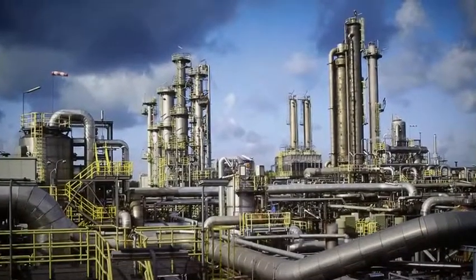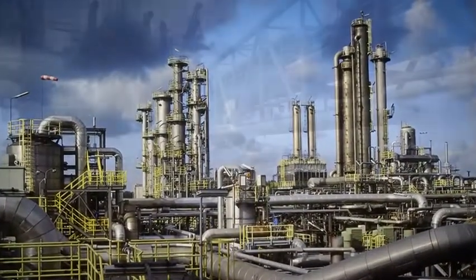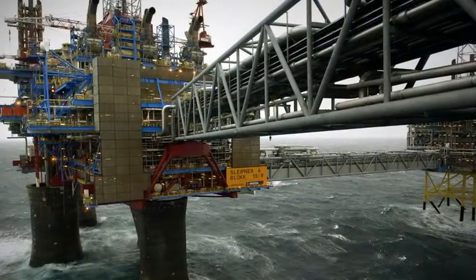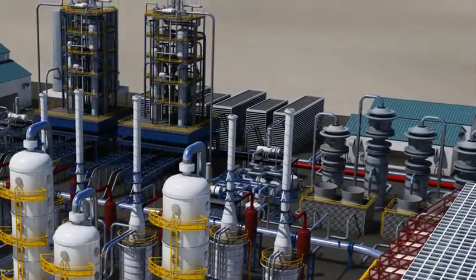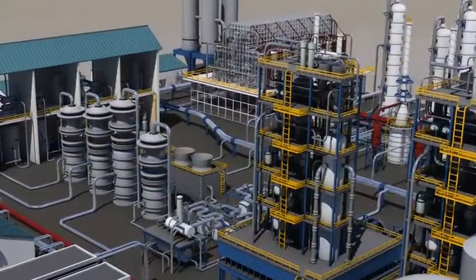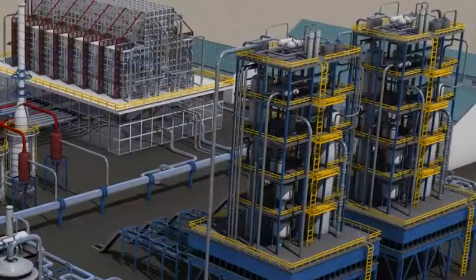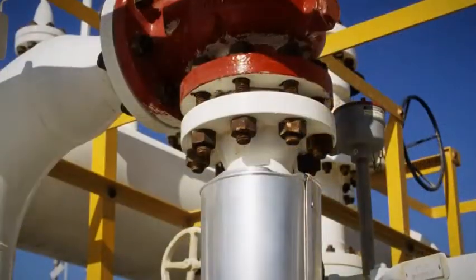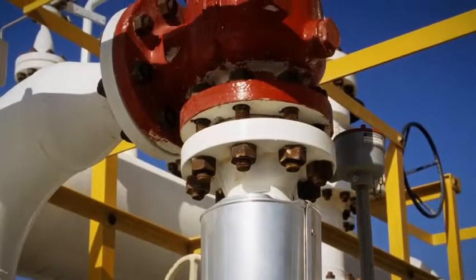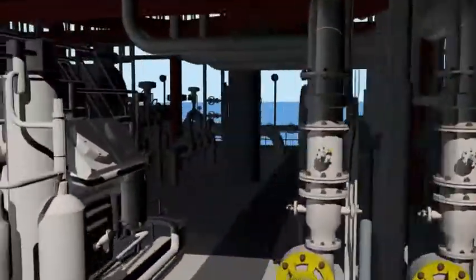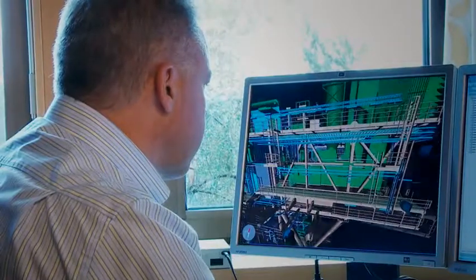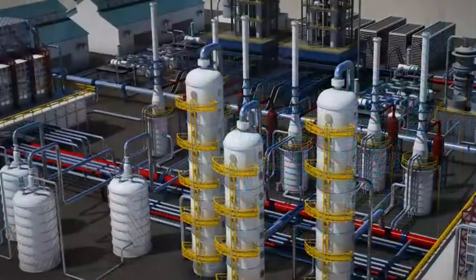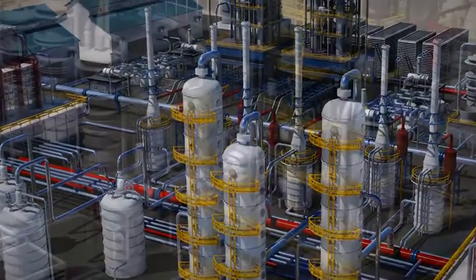Brownfield projects, those performed on existing plants, are the vast majority of projects now planned or executed worldwide. A brownfield project's workflow differs from a greenfield or new project's workflow in that the project must accurately model tie-in points to existing pipes and equipment for new equipment and piping relative to existing components and removal of components no longer needed. To accurately depict these tie-in points, a 3D model of the existing plant should be created.